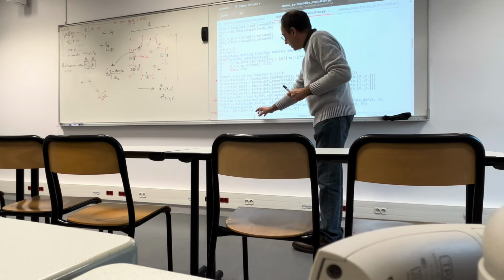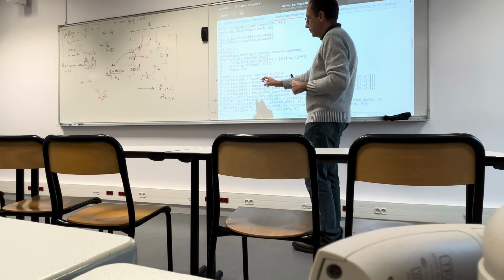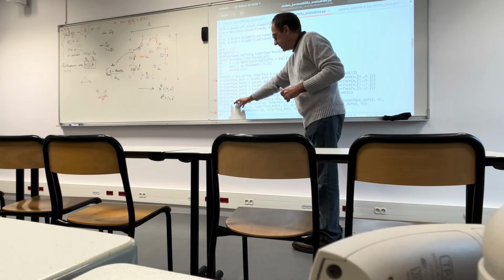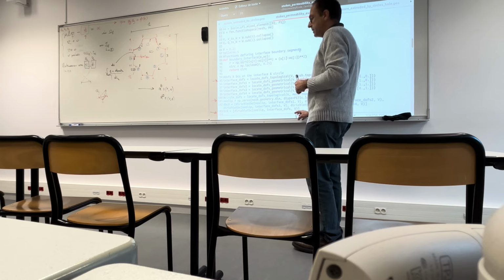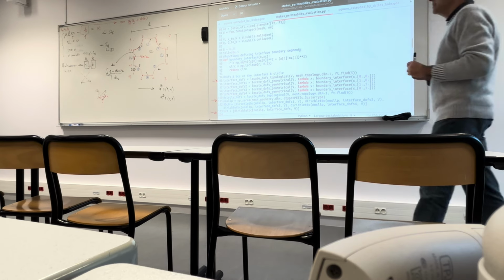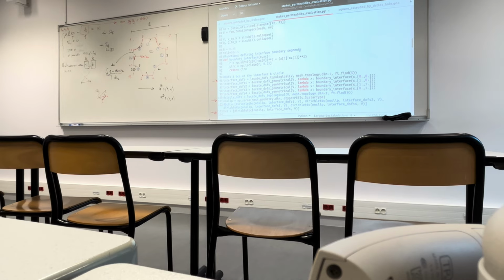BC naught is the Dirichlet boundary condition where, on the interface degree of freedom which we have identified before, no slip, which is this condition of 0 velocity, on the space V. So this is the way of prescribing 0 Dirichlet boundary conditions on the domain labeled as 5.